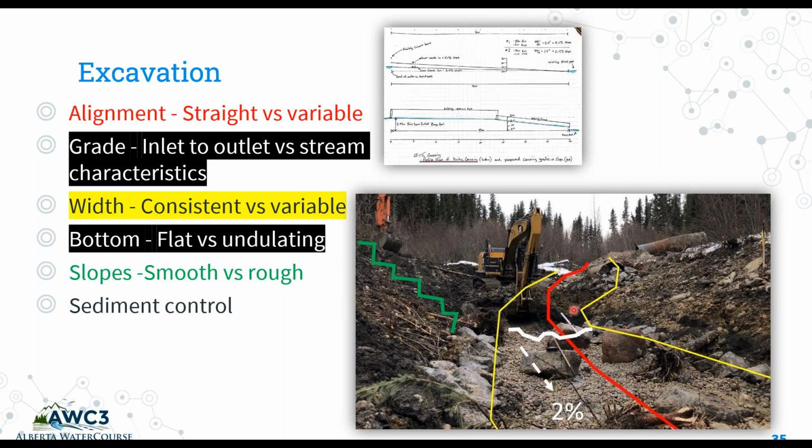You'll also want to leave your slopes very rough and lumpy. If you've got nice smooth slopes, you may need to work with your excavator operator and equipment operators that are trained to make things look nice, to make it look natural. During the excavation process, you might find buried topsoil, trees, or natural stream beds. So you may find materials you have to remove from the site.